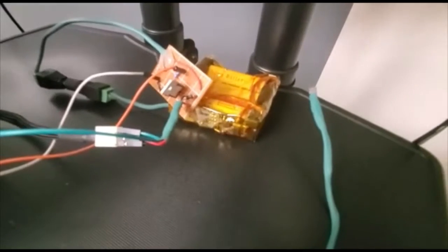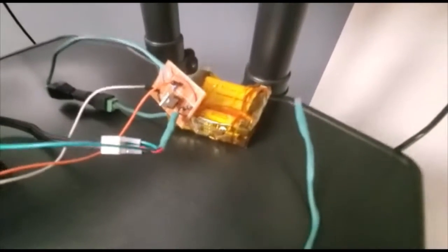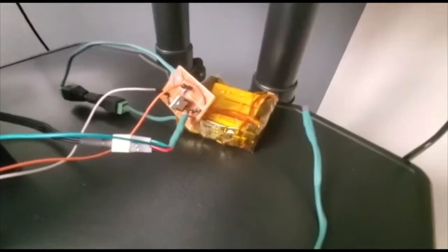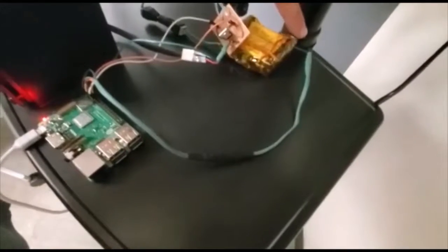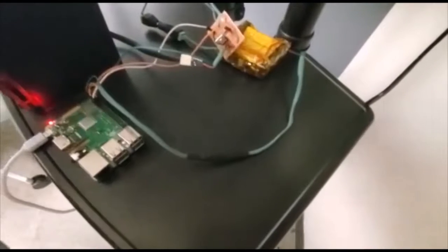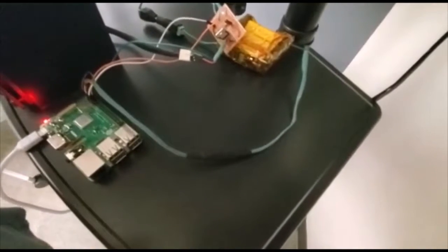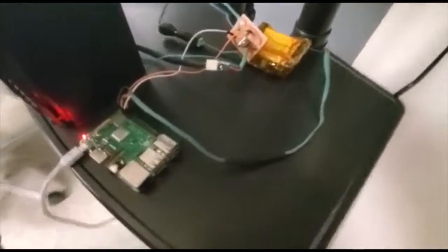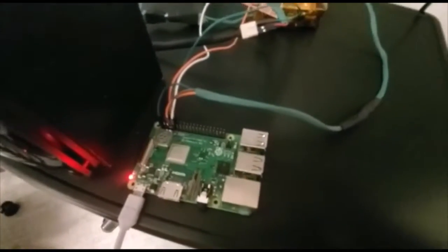The BMS module we have ensures that we have an output of 12 volts and maximum amperage of 10 amps, which is more than enough. The little thing right here is our temp sensor. We're using a digital temp sensor that runs on one pin of data and reads the temperature, which controls the speed of the fan while using pulse width modulation.